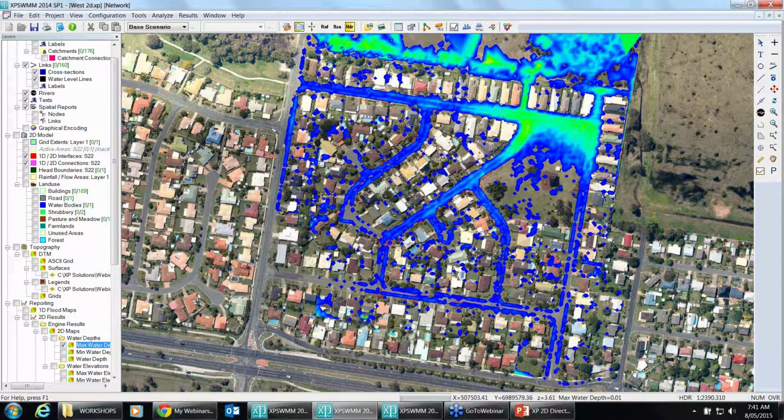So look, that's a very traditional comparison, I suppose. And in the graphs that Bill showed before, with that 3.5 cubic meters to 5.5 cubic meters of flow coming from this respective catchment, we would want to go back and have a look at the depths at key locations and other response points to inform ourselves of the suitability of which one is more or less right than the other. So that's again a nice flat model.